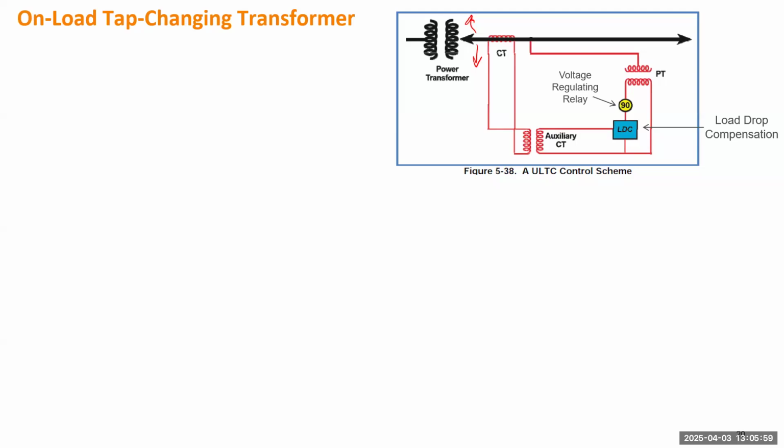And you can also add this component, which is very similar to the load compensation component you have, such as you can program RC and XC there, and RC and XC basically give you an estimation of the distance to the location where you want to control the voltage. Definitely this RC and XC can take either positive or negative values depending on which side you want to control the voltage. So this is basically like an excitation system, but the design is much easier.